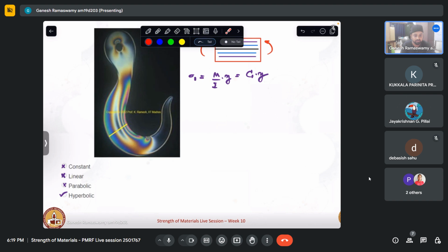Right. And does the direction of load application with respect to the curvature actually matter? Here, for example, I assume the load is applied downwards, but what if I applied it upwards? Would it still follow the same pattern, and would it still be hyperbolic? I don't see why not, because it has to be objective that way. Even in our derivations, if we were to flip the moments, only the nature of the stresses should flip. But it's an interesting thought. I'll maybe look into that, but I don't see any reason why it should change.